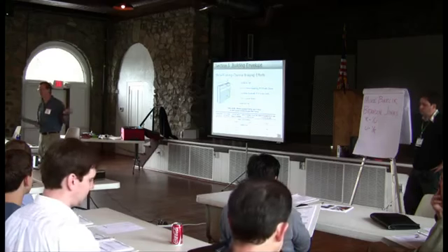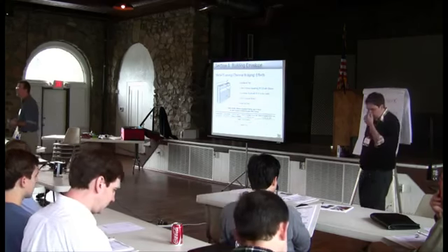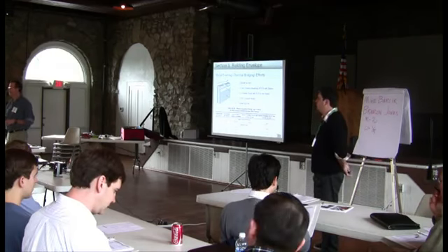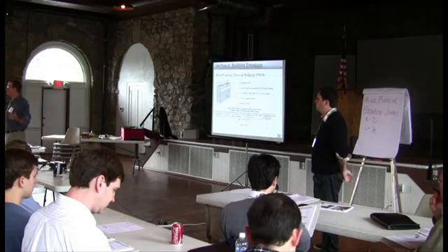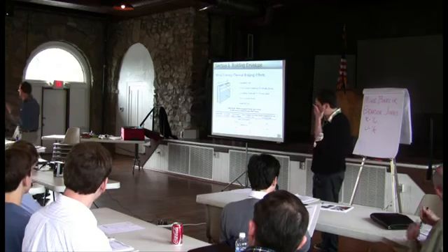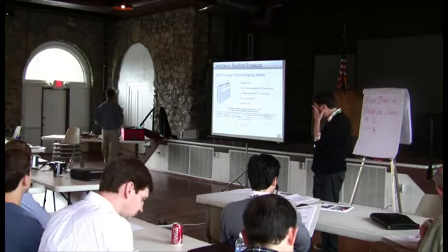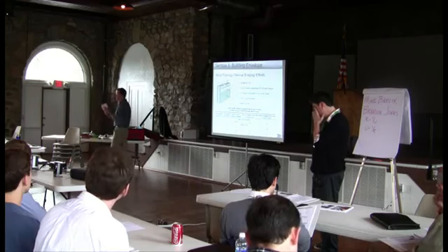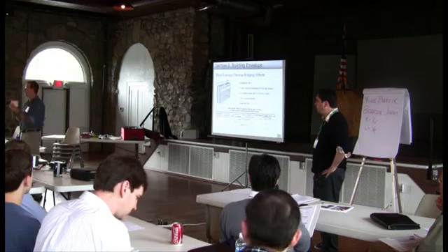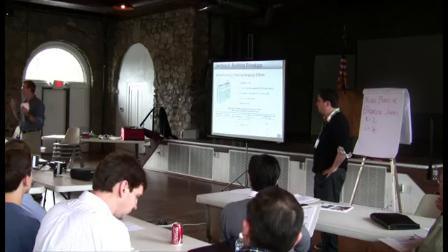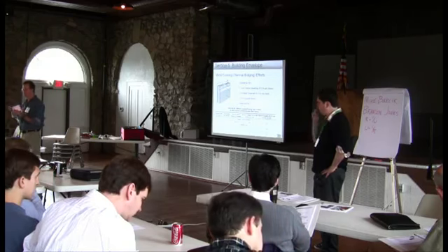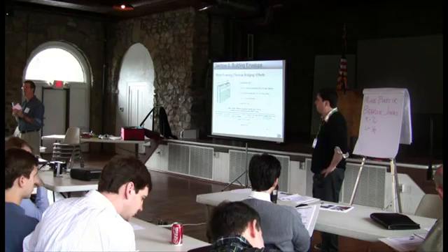The main thing is that the code takes this into account. And there's a very significant change now that occurs in the prescriptive code for everybody in this room in Climate Zone 3. And that short answer is that when you have a steel stud wall, they want R4 foam board on the outside. Because the foam board creates a thermal break. Be it pink, blue, whatever, the foam board creates a thermal break, and that's what they're asking for. Now, you can put exterior gyp and cover it with foam board, but that's the prescriptive code. That is the second really big change in this version of the energy code. The roof going to R20 and the requirement for foam board on steel studs.